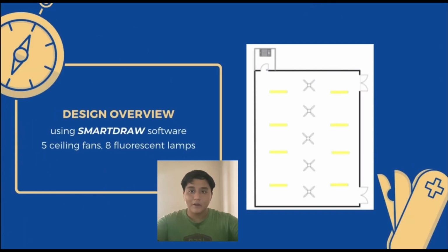In order to power the common hall, we needed to assess the power requirements for the lights and fans that will be used. The common hall will use 5 fans and 8 fluorescent lights. These power requirements will be used to design the solar panel array, battery bank, and inverter system to ensure that the system is able to generate and store enough power to meet the needs of the common hall. Additionally, appropriate circuit breakers will be used to distribute the power throughout the common hall and to protect the system from overcurrent and short circuit conditions.